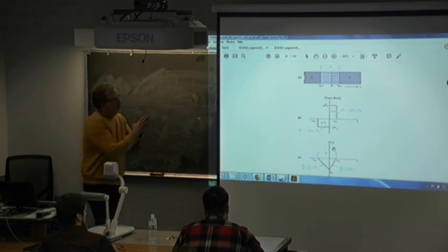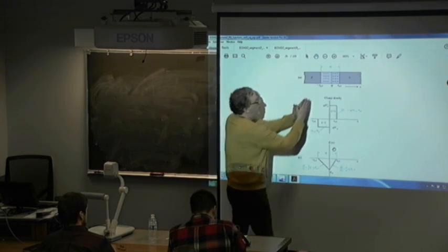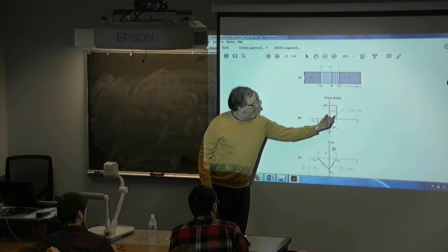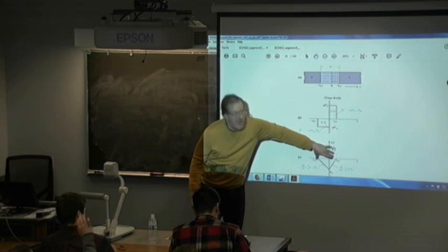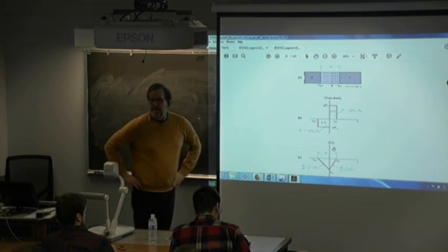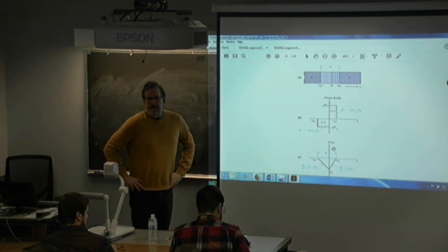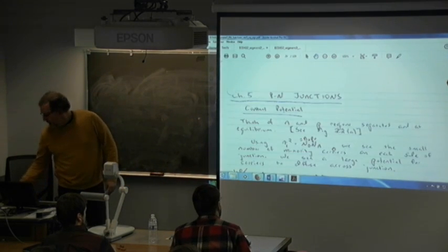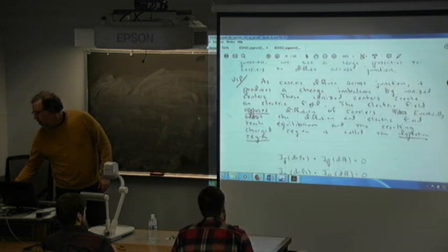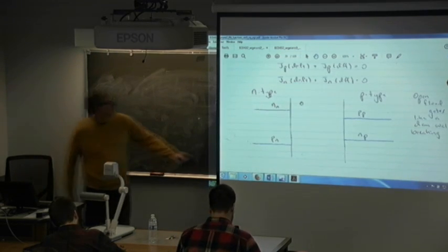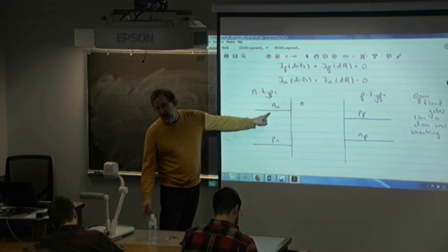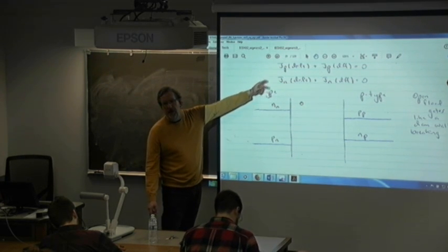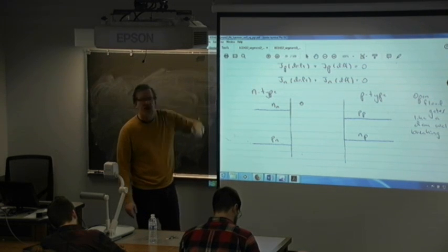So as it diffuses and it opens up, we're establishing this electric field, right? We're making this dipole, and we're creating this electric field. So what was the cause and effect for that last slide? I would argue that the cause is the concentration gradient, and the effect is the diffusion, which leads to the formation of the depletion region.